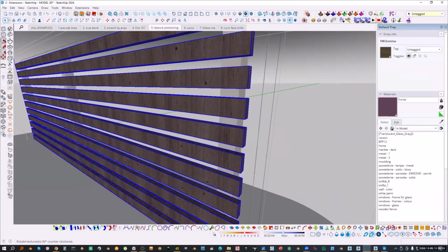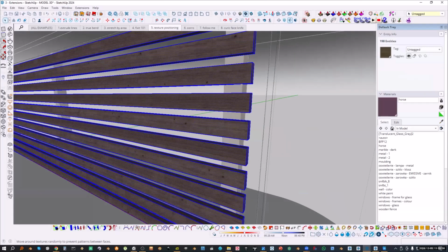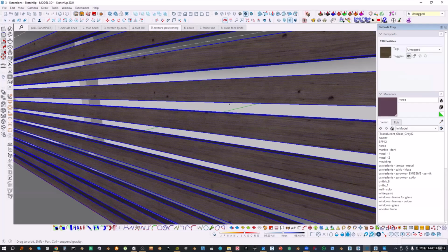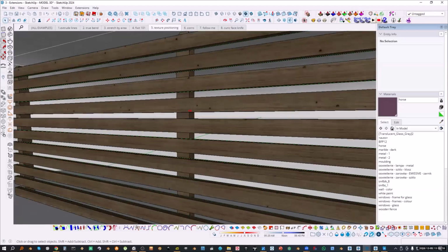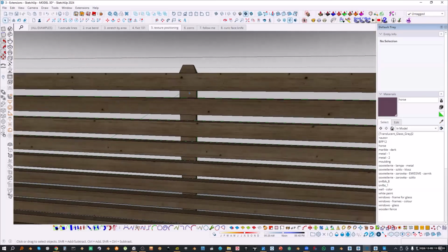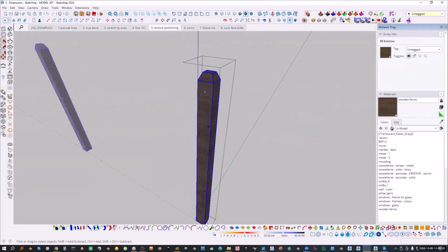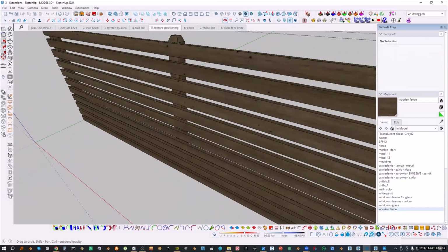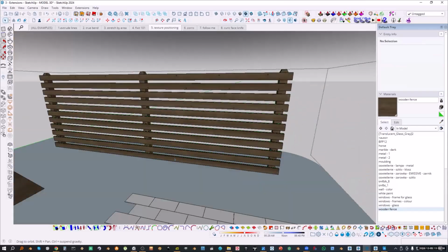So with this plugin, you just click once, and then we can depatternize that, which is here, the last option. It will randomly position those textures on the surface, which creates the illusion that those are actually multiple different textures, not just one, because this is just one texture, a wooden fence, some JPEG from the internet. And also here, we can do just a 90 degrees rotation, and the fence looks much better now with the correct position of the texture.